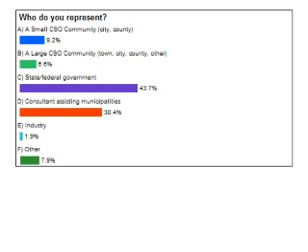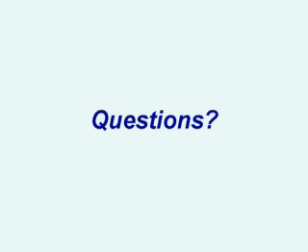They're still treating that. Atlanta has a bigger problem in that the capacity of the river, Atlanta's at the top of a watershed, and the capacity of the river to assimilate all the waste, including the wastewater treatment plant discharges, is used up. 80% of the load now, the capacity of their river system is taken up by sediment oxygen demands that come from stormwater runoff. So what Atlanta's doing in their tunnel system to capture all these flows is good for the river system itself. Stormwater is being considered, and in the future in Atlanta will be a big thing to take care of, to have the capacity of the river to assimilate wastewaters.